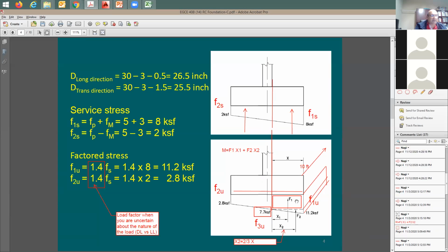I decide here to split this force into two forces, F1 and F2. It is true that I can find the force for this trapezoidal distribution. I can do just one force. If you want to, I should be able to. You know, this area of this trapezoid. The only problem is going to be the point of application. How would you find the point of application or the CG of this trapezoid? So someone's going to say, yes, it's true, I can do one force like this. You say, this is great, but how about this distance? You cannot find it that easily.